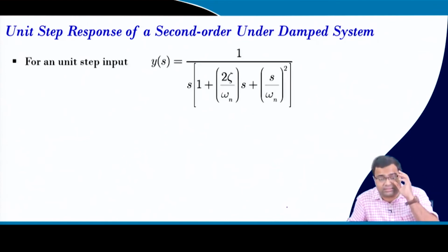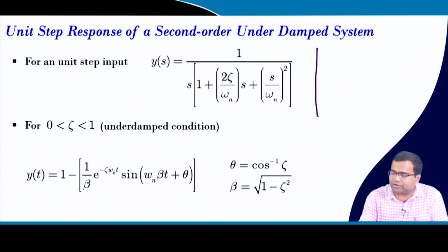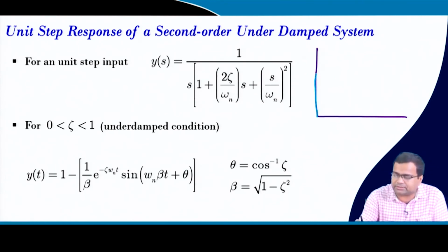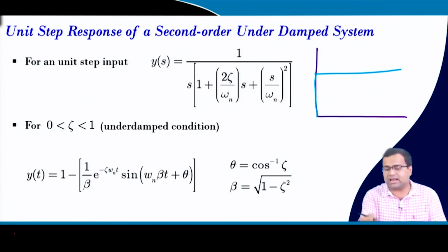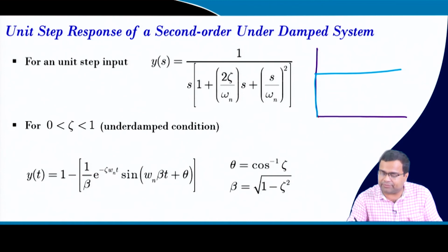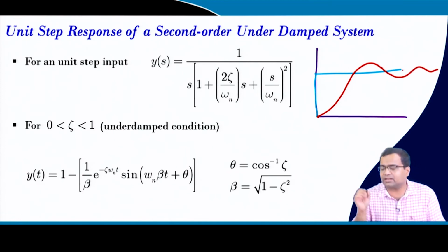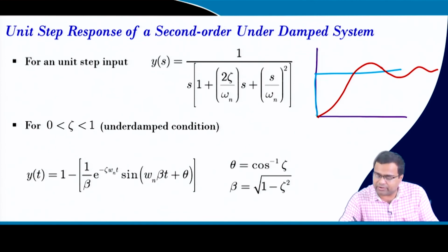Similarly, if you take the second order system response, then you can find out depending upon the damping ratio. So, you can draw the plot, we have studied this in the control system context. If you apply a step response, if the K_DC equal to 1, here it is a unity gain, then you will find like this, and if it is even overdamped, then like this.